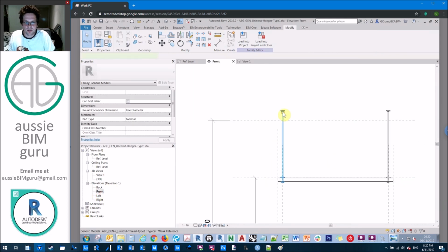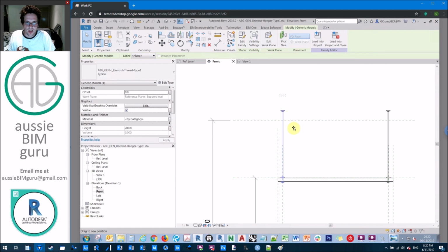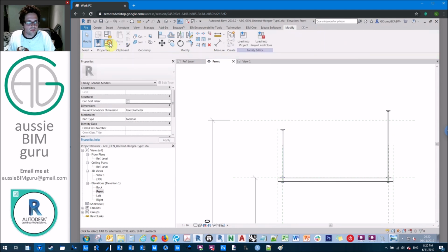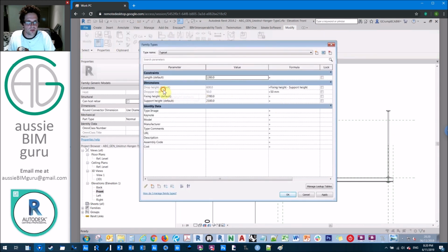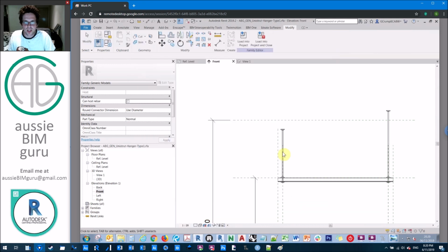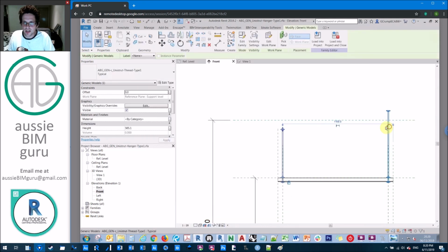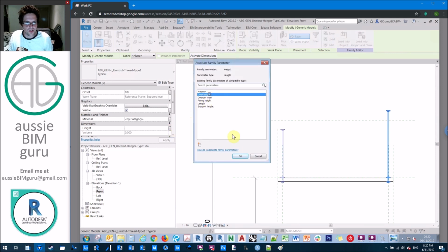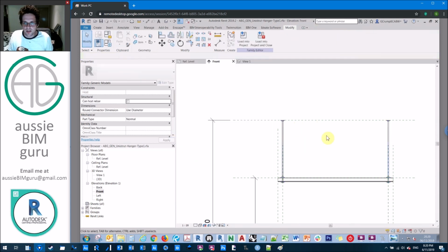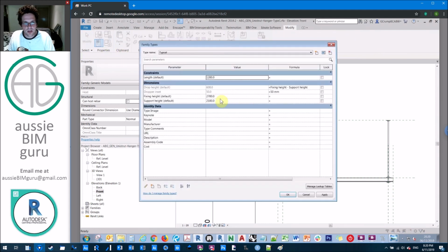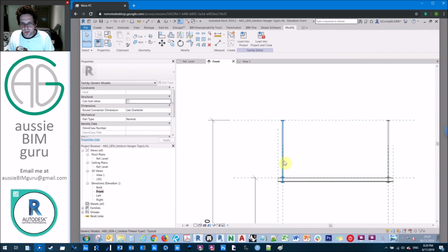But the one thing we haven't connected here is that these threads are currently flexible. But remember that we created the parameter for the drop height based on this formula. So you can actually nest this into the height of the unistrut. So even though it's driven by a formula, you can use that formula to drive other elements. And now you'll see that this remains parametric. So when we raise or drop our unistrut, you'll see that our components also follow this height as well.